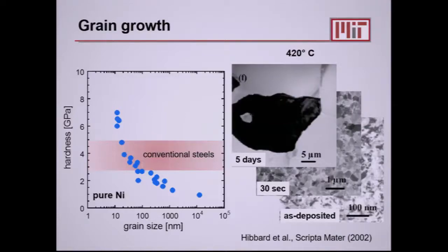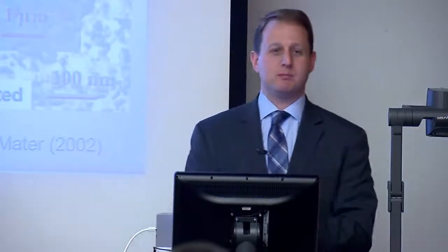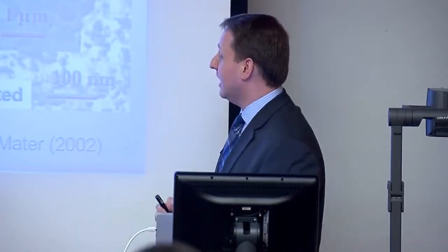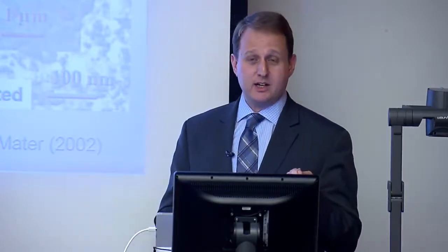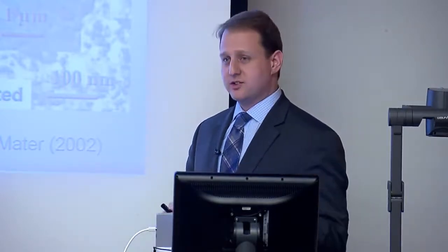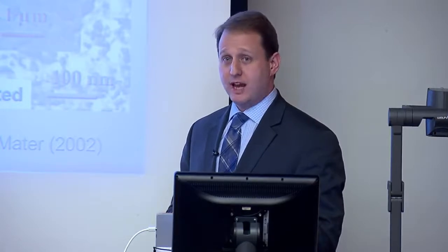So I know what you're thinking. You're thinking, my Pimpmobile rarely sees 400 degrees C. I'm in Cleveland. It's pretty cold here. It turns out that this problem, it's thermally activated. It's grain growth. If you cool things down, it happens more slowly, but it still happens.